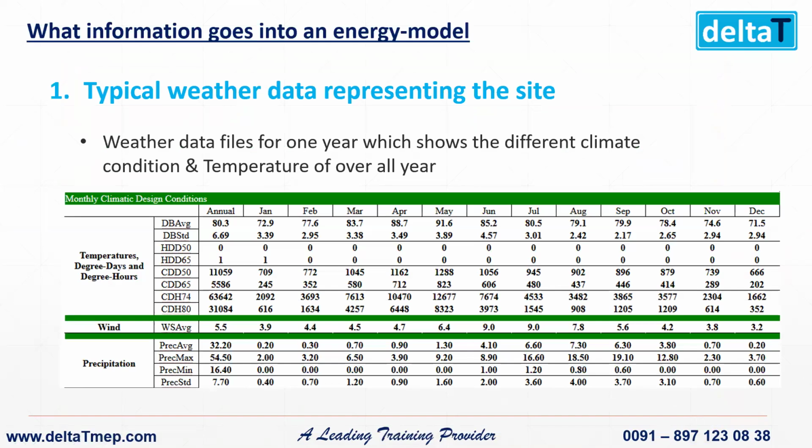Generally, we do HVAC design, or I can say AC selection, based on the peak load. What does peak load mean? From January to December, we have different temperatures, right? So if you see this one, January to December, we have different outside temperatures. Imagine in Bangalore, the temperature goes approximately 36, 34, whatever. In Fahrenheit, if you see in May, the maximum is 91.6. So generally, we design based on 91.6.